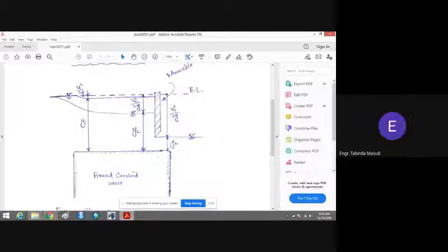When you close it, it will join the broad crested weir and it will raise the water level on the upstream side, and when you open the gate, it will allow water to flow towards the downstream side. You can see this is the upstream side and this is the downstream side of the channel. First of all, when the gate is closed, you can see that this is the level of water. For this level of water, the velocity head is very small, because the water will be almost in static condition here, or you can say the approaching velocity will be zero.